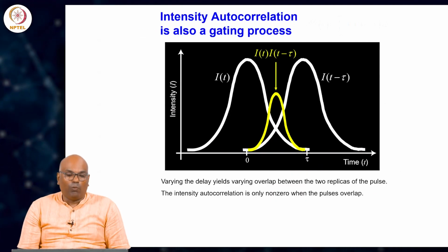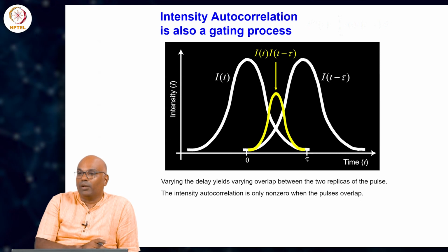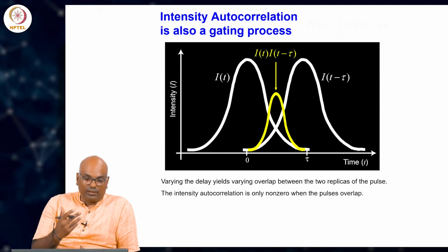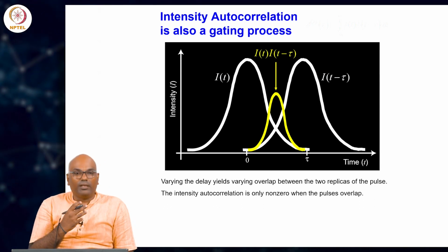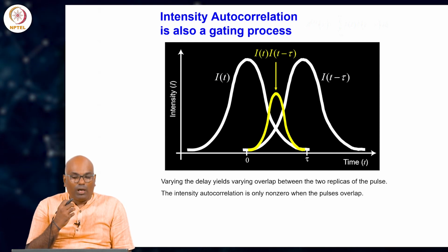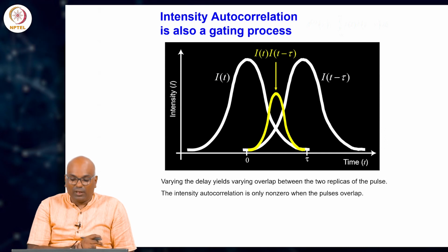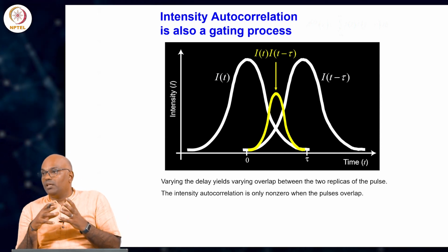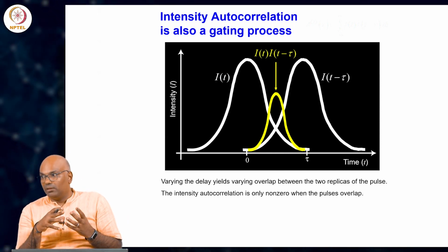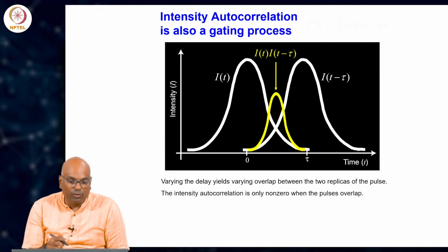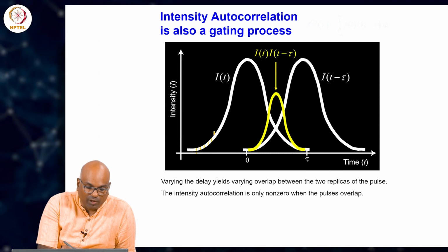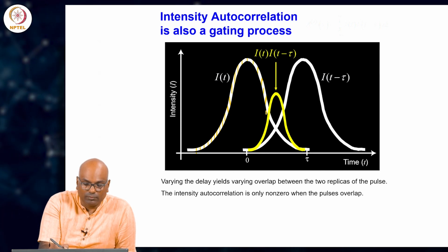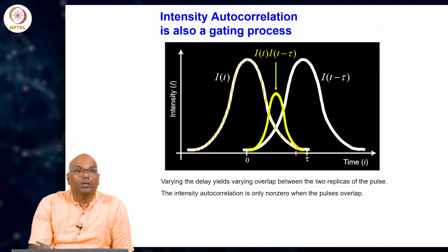So, getting past that, why is autocorrelation working at all? We want to step back and examine, in the case of laser pulses, this very fundamental principle of how I am getting some information about the pulse itself. Where is the function and where is the window, where is the gate, right? How am I able to visualize, how am I able to slice this very fast signal in time and get information about it?